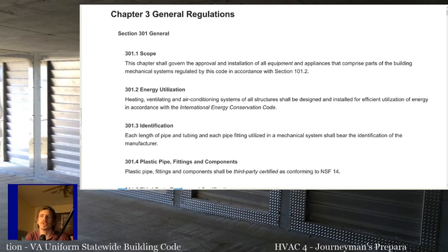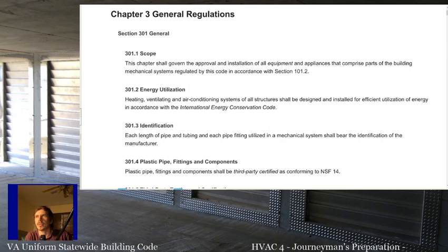The maximum size hole in a 2x8 joist should be blank, right? Well, to figure that answer out, you're going to need to know that a 2x8 joist is really 7.5 inches, so you need to understand that the true depth isn't the actual depth, right? And then you need to know what percentage the code allows you to drill in a 2x8 joist. So you do have to do a little bit of math for something like that, which I'll give you the answer for, and we'll go over. But the majority of the questions are just basically find the missing word in the sentence or find the word that matches the sentence. You should be able to see the exact answer without a doubt.